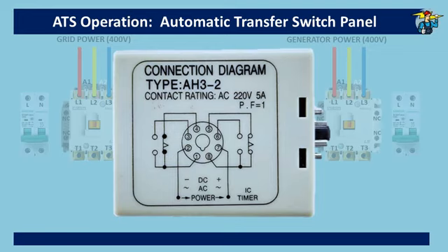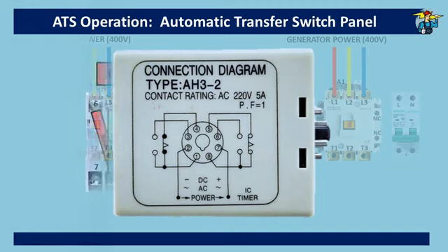AC or DC power will be connected to these points. 1 and 8 are the double pole input points on it, as indicated by the first two letters of DP/DT, or can be called common points. 3, 4, and 5, 6 are double throw outlet points of 1 and 8 respectively.